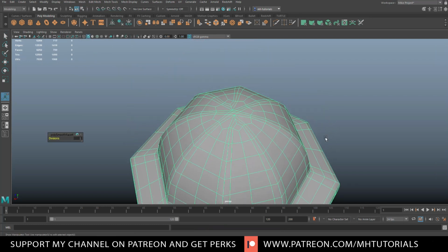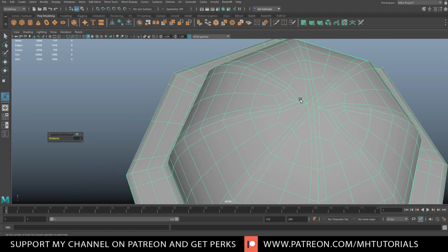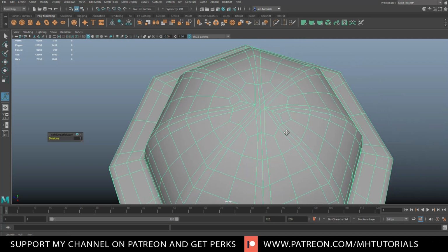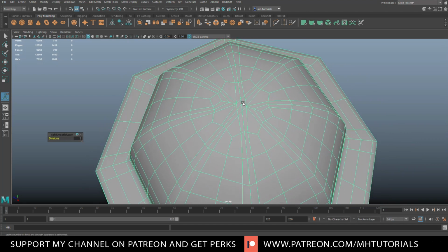Let's see if we got any n-gons here. I don't think so. Let's see, 4, 4, 4. Yeah, we do have triangles, which is okay. And if you are not happy with that, you can obviously sort that. And yeah, we don't have to, but you could.